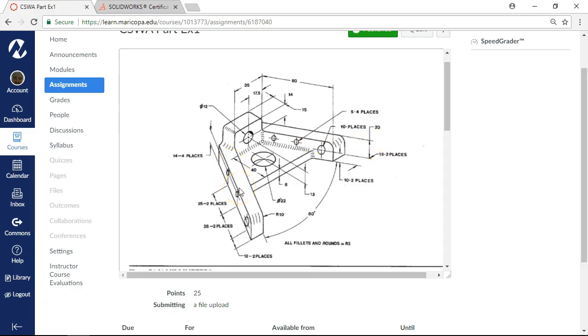So our strategy is to start drawing individual pieces and extruding them, or do we want to use the contours and regions? So identifying what is going to be helpful as contours and regions, if I can draw as much of this sketch as I can and then share those contours, share those regions between features, I'm going to be able to save a little bit of time.